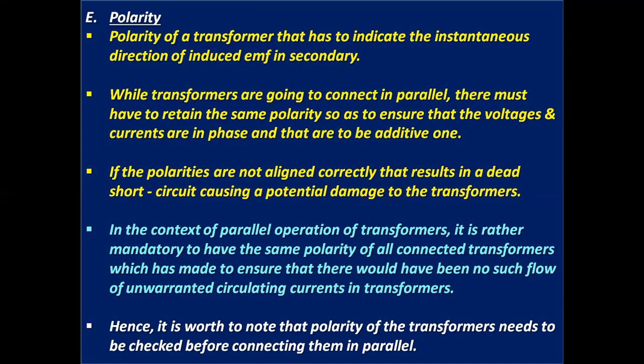In the context of parallel operation of transformers, it is mandatory to have the same polarity of all connected transformers, which ensures that there would be no flow of unwarranted circulating currents in transformers. Hence, it is worth noting that the polarity of the transformers needs to be checked before connecting them in parallel.